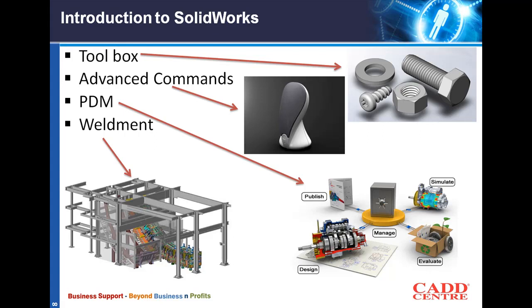This structural design and fabrication of assemblies you can do using SolidWorks in a user-friendly way. For these types of assemblies, the first primary requirement is the information about the cut list. That is, when I create the whole design, how many structural members I will use, and what the length of the individual members is, and all this you can achieve as simply as possible in SolidWorks.